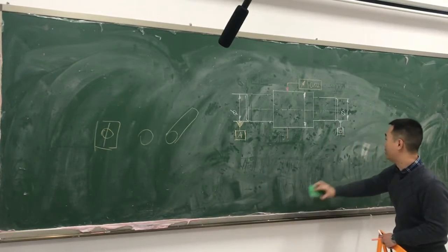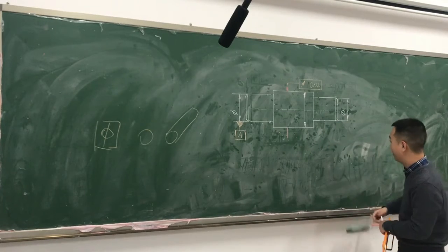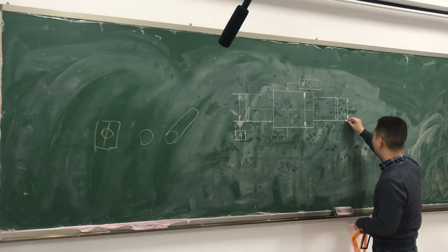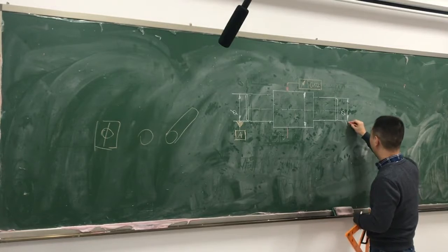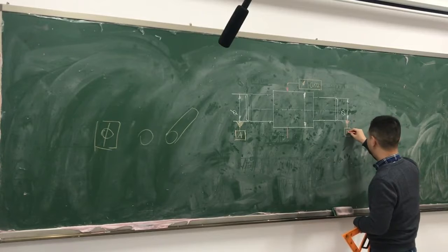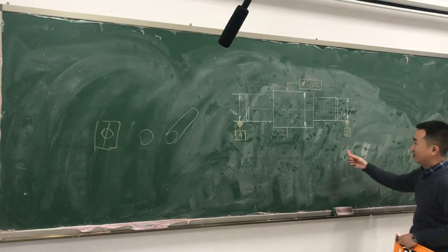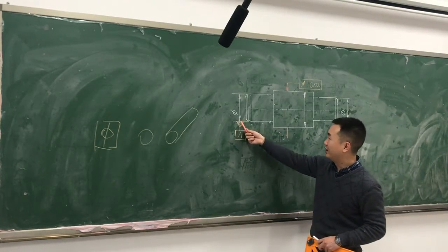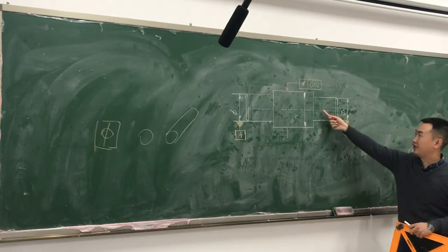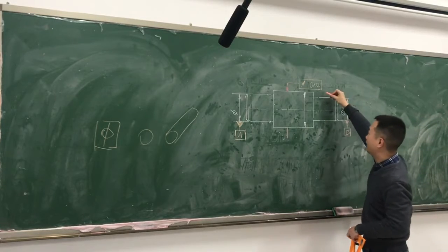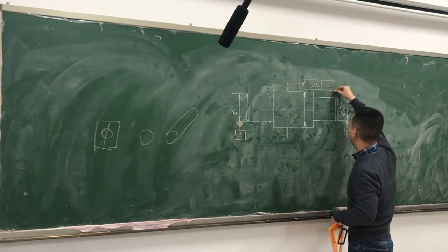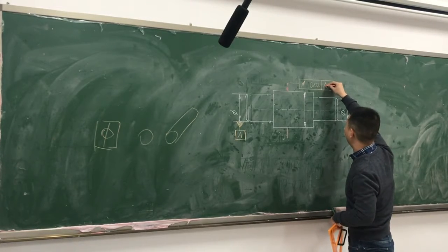And you should also place the datum here at the dimension place. So this is datum B. So this means datum A is the axis of this cylinder, datum B is the axis of this cylinder, and the datum for circular layout here should be the common datum A and B. And so we write down here.